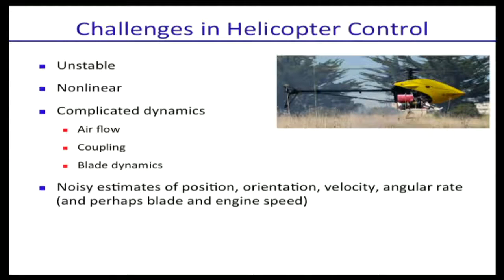Same thing with a helicopter. In fact, it's extremely similar, because the way you move a helicopter forward is by tilting the nose down, because you only have vertical thrust. You don't have forward thrust or sideways thrust. Same with the glass plate and the marble. You actually have to tilt the nose of the glass plate down, and then you can move forward. Assuming you can only apply a vertical thrust to the glass plate, of course you do a little more there, you actually get the same setup as your helicopter.